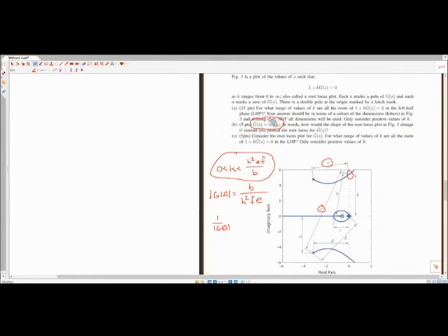So this is showing the critical value of K, where the poles go up to the right half plane. But the shape. If I were to plot the root locus plot for 5 G of S with these blue lines, the locations of all the blue lines. Would it not change because the 5 wouldn't affect your poles or zeros?